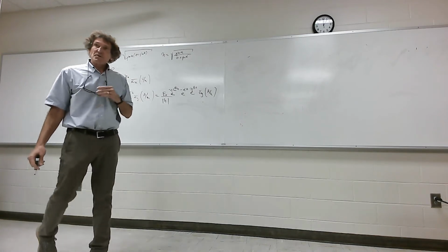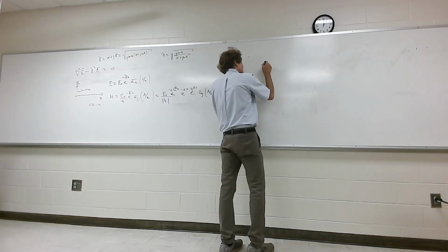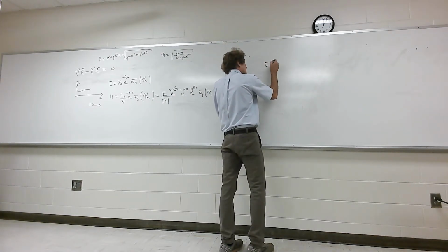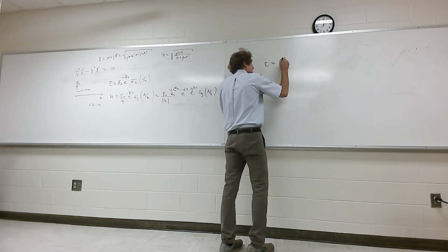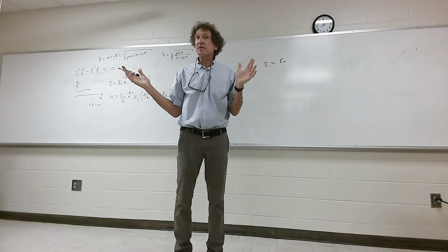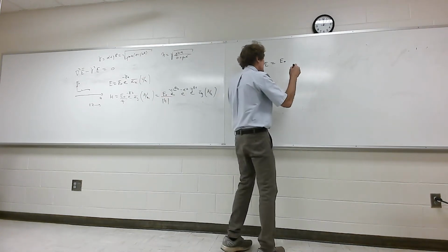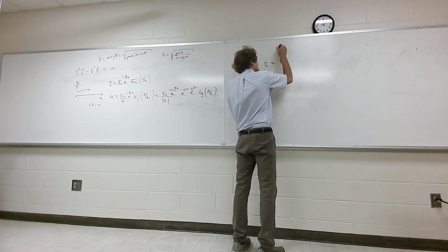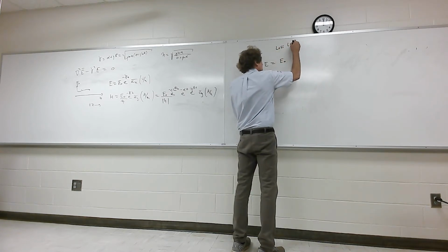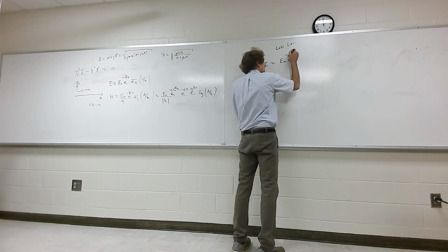Now in general, when you have propagation, this is the way it's always written for a wave. If you have a wave, and I'm going to use an E field, the E naught is nothing more than the magnitude. It has nothing to do with the direction or the polarization. Do y'all follow? After that, you're going to get a term, and let's assume it's lossless for now. You're going to get e to the either plus or minus, but I'm going to use minus j beta, and then some direction.